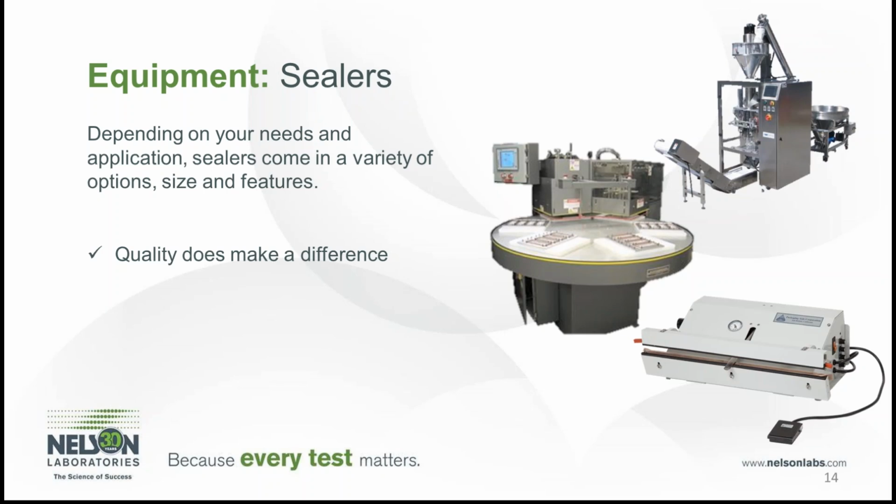The operation qualification, or OQ, looks at establishing the actual operating window of the sealer, establishing that nominal setting. Usually this is accomplished by looking at the minimums and the maximums of the sealer to help narrow in that operational window. Finally, once you've identified the window that the sealer needs to be operating in, you move into performance qualifications, or the PQ.